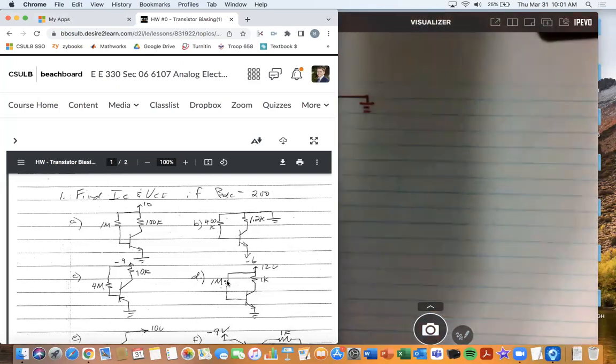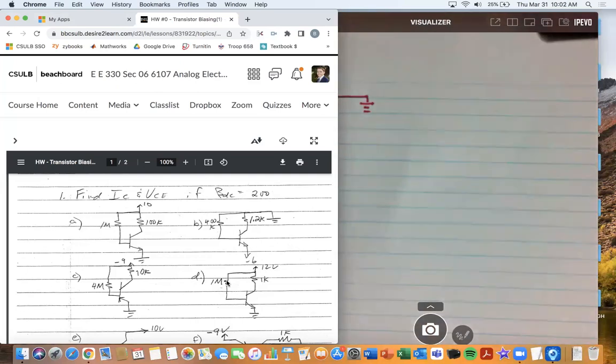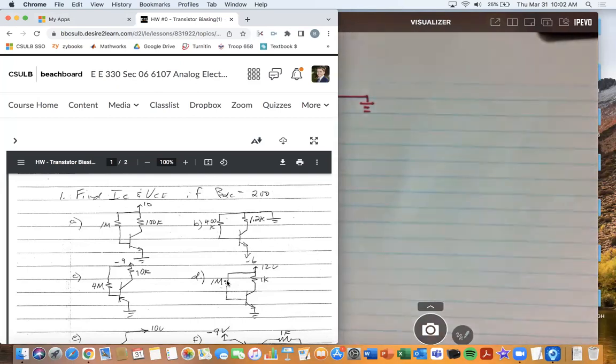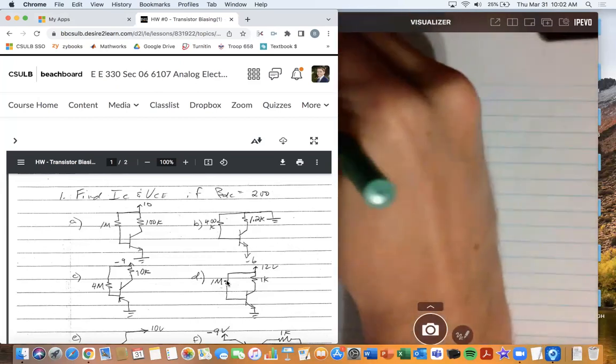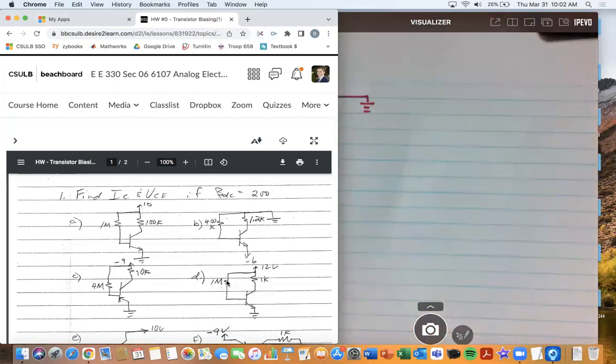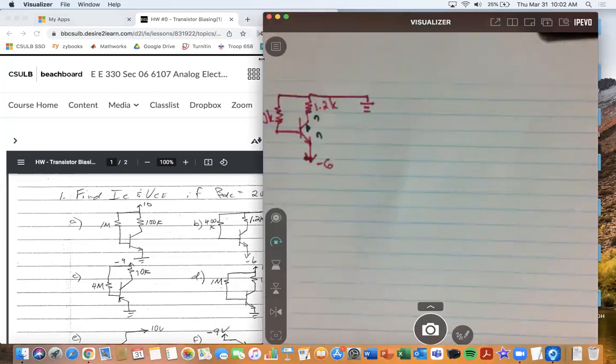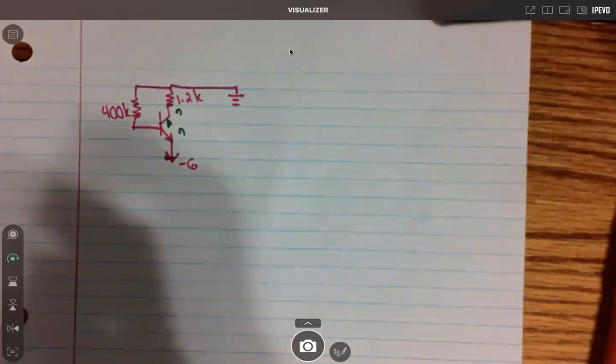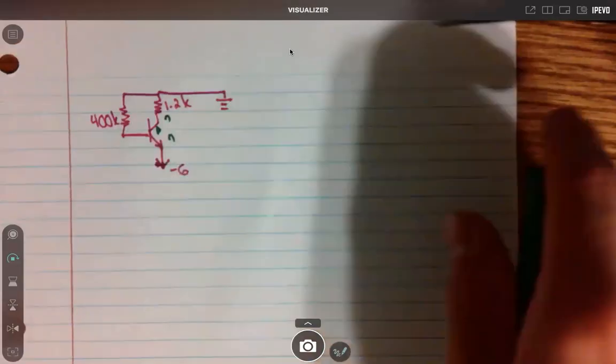And so how would we go about solving this? Well, first we gotta determine the transistor type. This is NPN, so that's great. And when we should be solving this, what I should notice off the bat is that I don't want to work with negative voltages, right? Because this is an NPN, we should be dealing with positive voltages. So therefore, I'm going to redraw this circuit because I'm going to make this, which is right now at 0 volts.